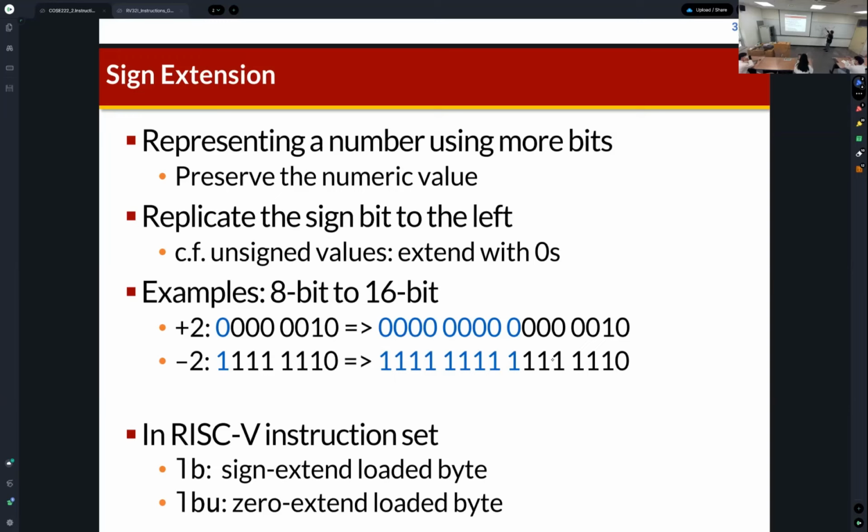Put -1 multiplied by 2 to 7, and then if we calculate the magnitude of this part, we can find that this is actually the same. Okay, so if this instruction handles signed data, and we need to extend the bit resolution of our data, then we need to consider the MSB to expand the bit resolution.